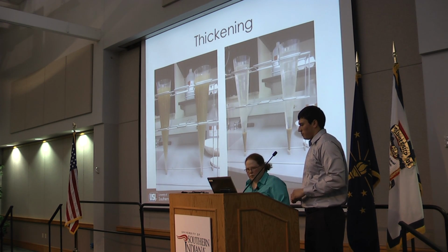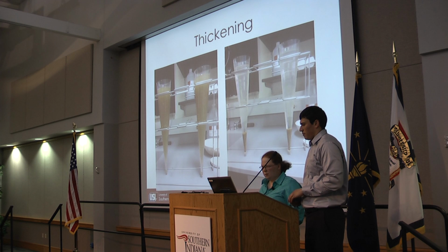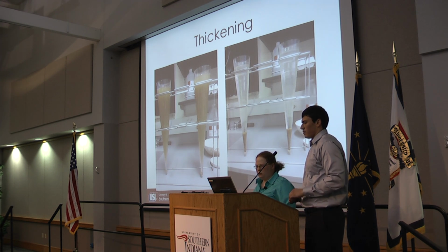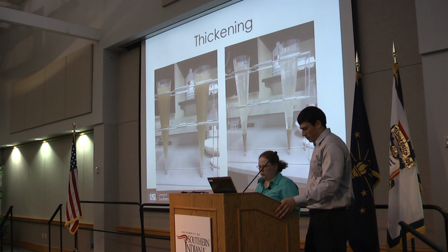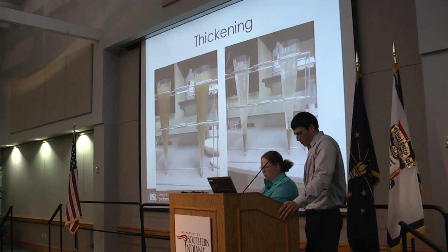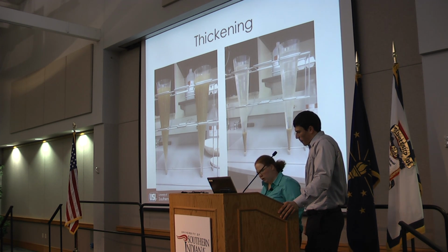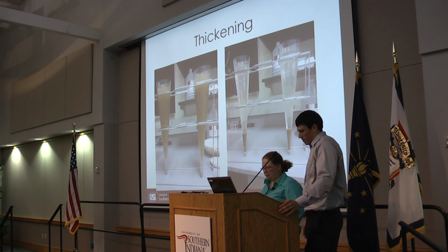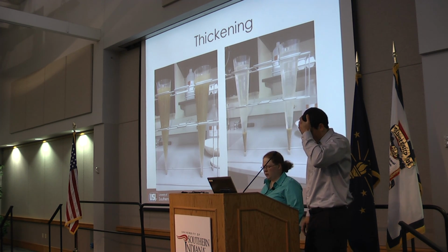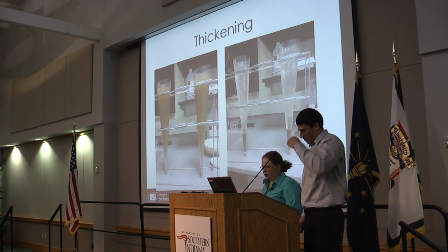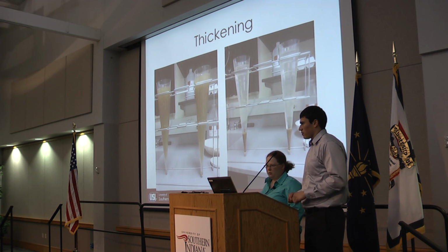To simulate the thickening process, we mix the 3 waste streams in proportion to what they should be leaving the equalization basin and place them in mop cones. Basically, it's to simulate the process of thickening, which means it went from 0.15% to 1.5% solids after thickening for several hours.